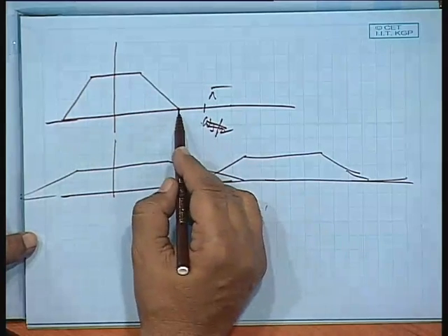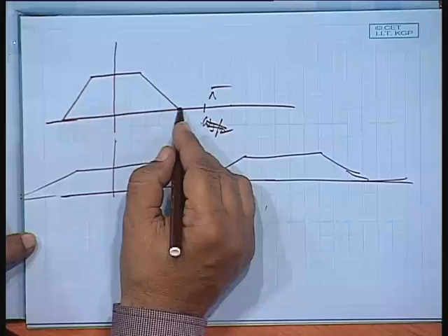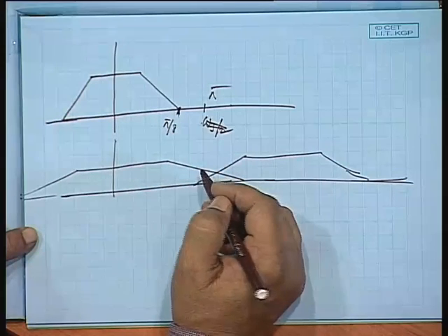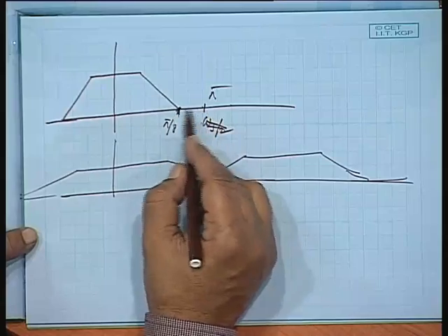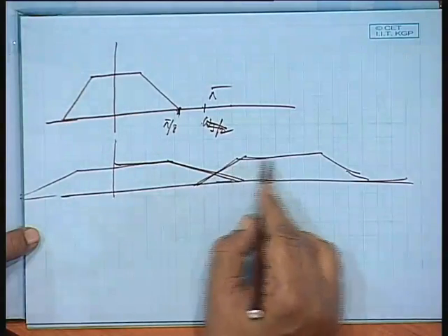So, you can downsample by a factor m such that m times this should be contained in pi. Suppose this is already given as limit pi by 8, then I can expand it by a factor of 8 when it will be just touching pi. If I downsample it by a factor more than 8, then there will be an effect like this.